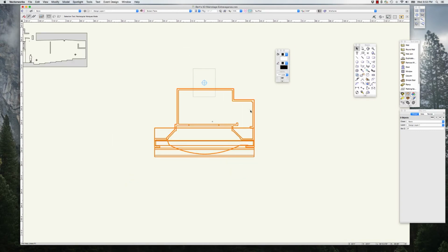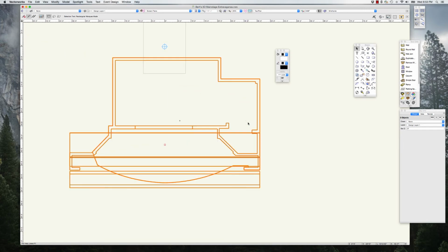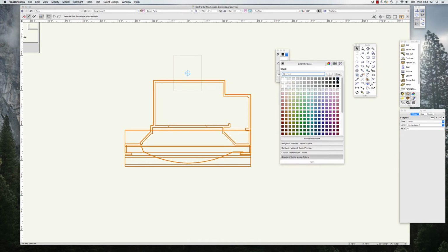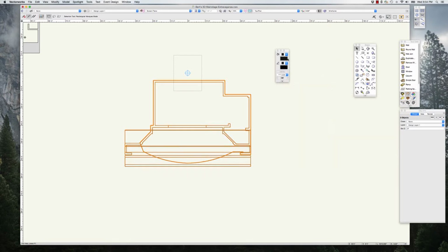If I made the walls of the theater black and put a ghost light on the stage, it would look like just a solid black rectangle. Unlike in real life in the theater, if the theater's empty and everything's painted black and we put a light on, you can still see the walls there, right? So instead of making the walls absolutely black, the last color here, which is black, I'm going to set them to 90% gray instead. So they're going to look like they're black. I mean, if you look at this, it looks almost like it's black, but they're still going to show up a little bit. So you'll be able to see the edges of the walls and things.